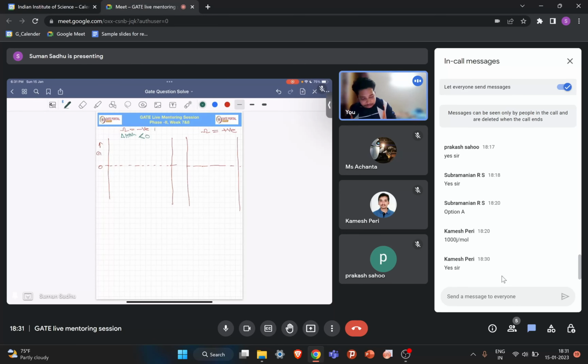So in this, let's say this is G, H, and S, T, S. Okay. So what will be your delta H? Then it will be negative. So it will be in this direction, and it is also a symmetrical function with your x. If you see, delta H is omega into XA into XB. So it will also reach maximum or minimum at x equal to 0.5. It is also a symmetrical function. This is delta H mix.